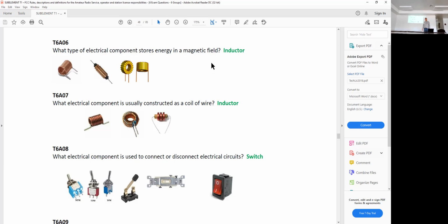Anybody know? They're filled with coolant, yep. But that's a transformer. And what's inside of that is basically 2 inductors. There's one with a whole bunch of turns of wire, and then another one right next to it with fewer turns of wire. And so they're magnetically coupling energy from that high voltage line into a low voltage line for your home to consume.